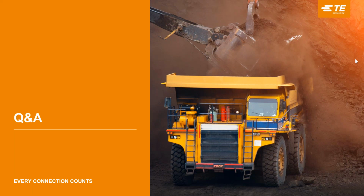So IP67 is immersion, up to I think it's 3 meters for 30 minutes. So there is an immersion protocol for IP67. A lot of these connectors we have either tested or plan to test to higher ingress protection requirements. The Enet Steel Plus, for example, also has passed the USCAR 2 specification, which has not so much a depth requirement, but goes through a much longer period of preconditioning, and then has pressure vacuum testing, both outside to inside and inside to outside.